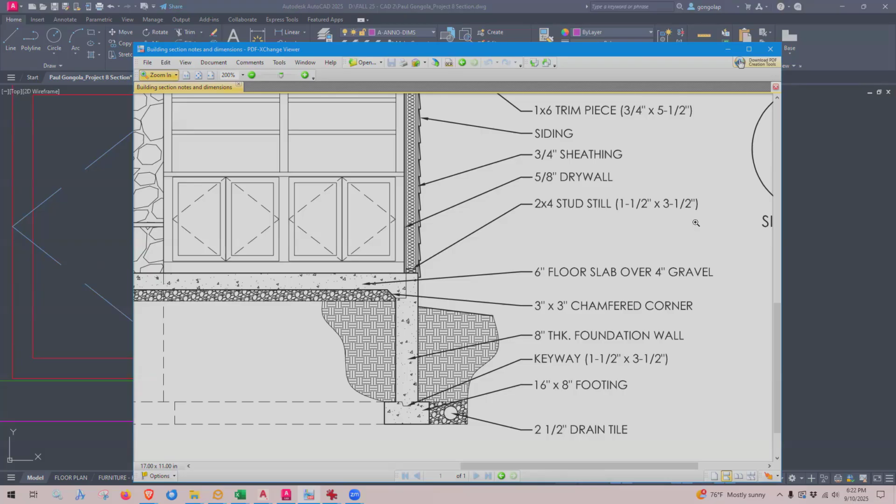Well, first of all, when they are cutting the wood, it's cut a little bit smaller, and then it goes into a kiln and dries. In the drying process the wood shrinks, and then they do a second honing to get a more precise dimension. So the actual dimension of a 2x4 stud is 1.5 inches by 3.5 inches.